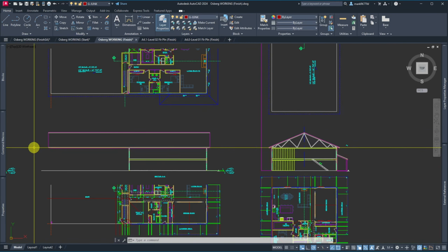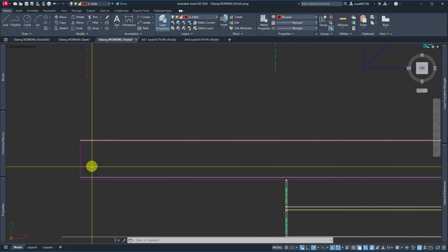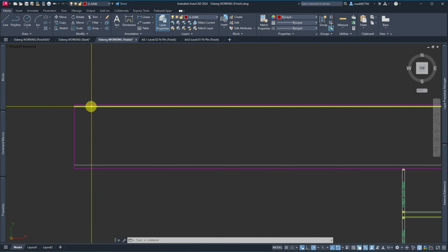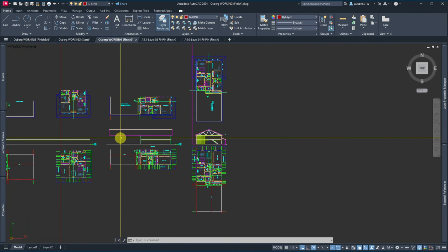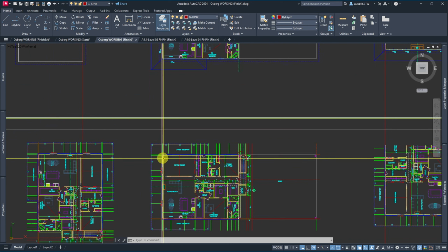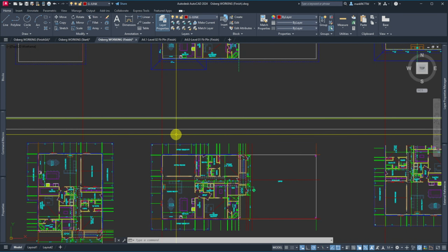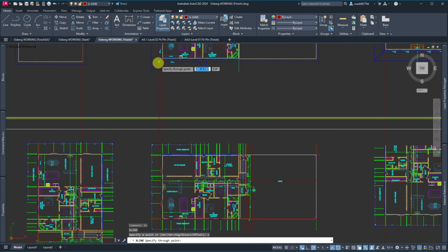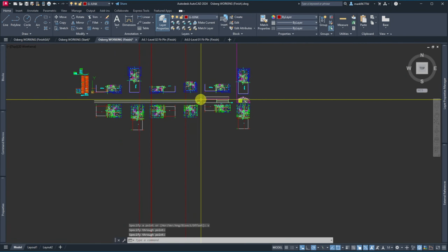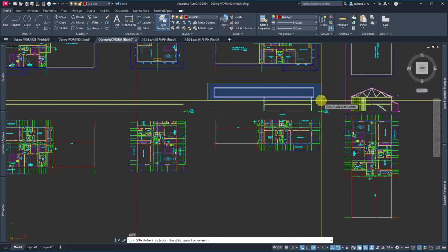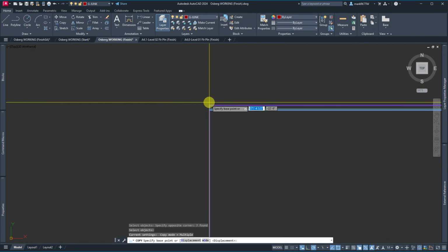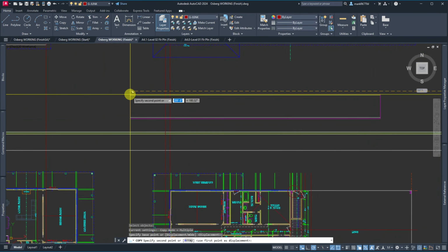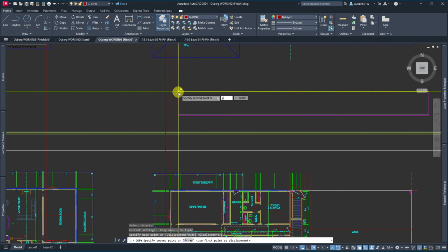I'll show you another little trick. I use this in elevation. We wouldn't see this in section. In fact, I wouldn't even see this fascia in section, nor this ridge. But I will copy this over to my elevations anyway because it's the same deal. So if I do X line vertical, put that in here, and then I copy this. I'm going to leave it here because even though I don't need all these details, I will need the outline of it. And then go perpendicular.